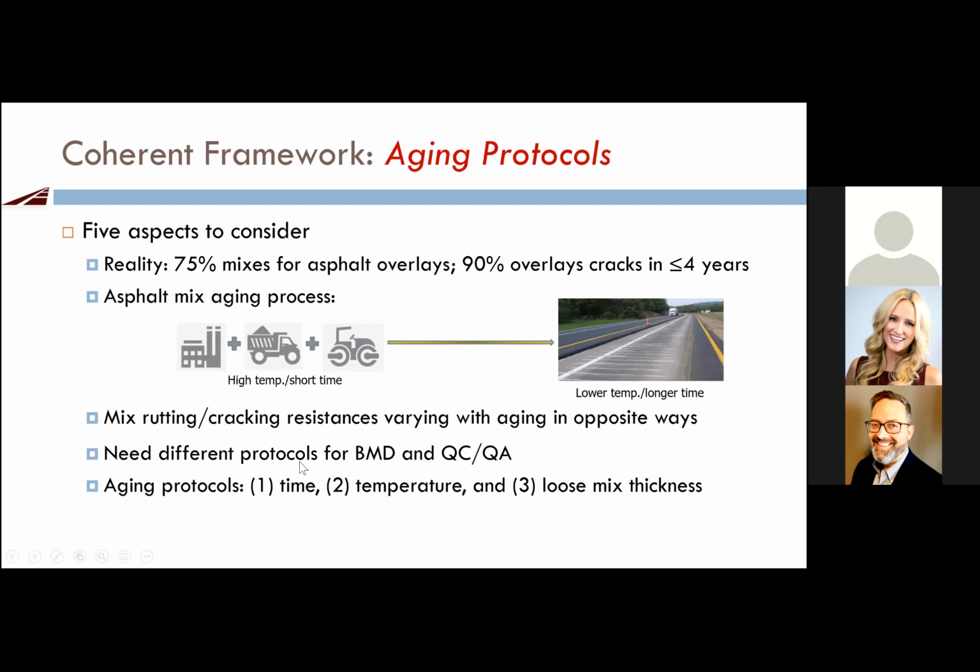Again, we need different aging protocols for balanced mix design stage and QC/QA, because for the QC part, we only have an hour we talk about. We really need short term. We cannot afford to do long term during the QC process. But for the BMD, you have time. Yes, you can do it.